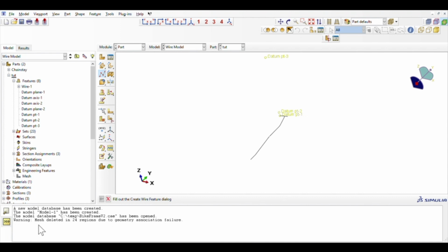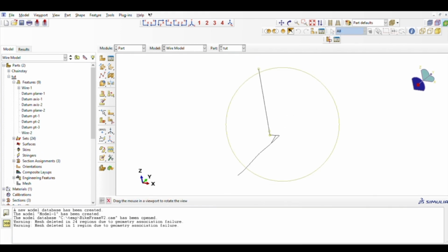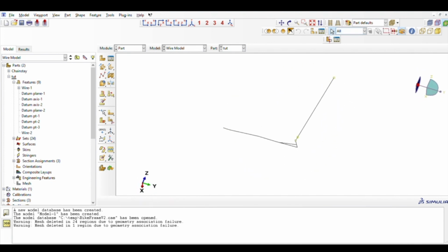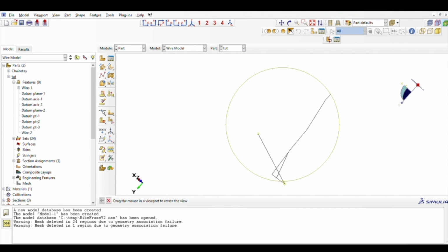Here I want to disjoint the wires. That just means you won't click and it'll start creating a chain. I'm going to hit plus here, click on my first point, and then my second point. I'll hit done. And so now we have a bunch of 3D points that are connected by lines. And these are all wires. So I'm going to build the rest of the model and come back when that's done.